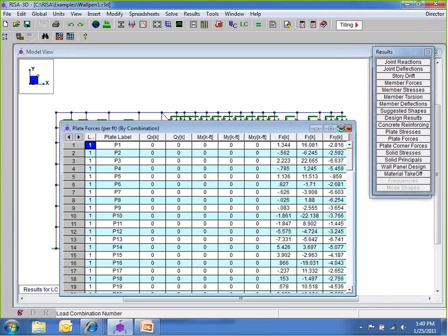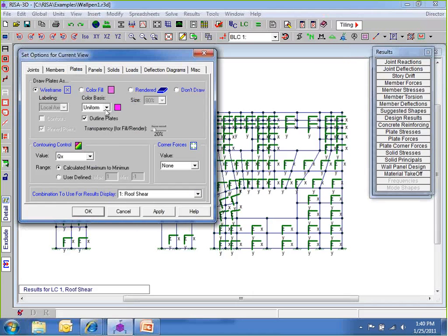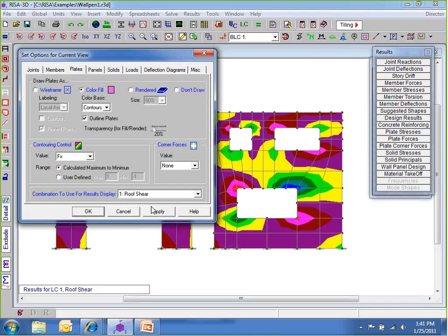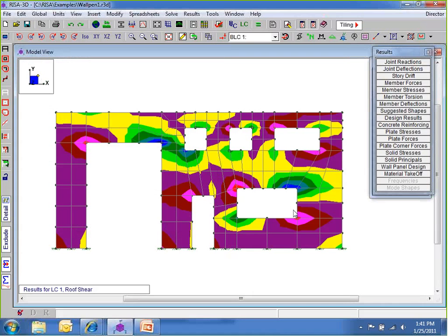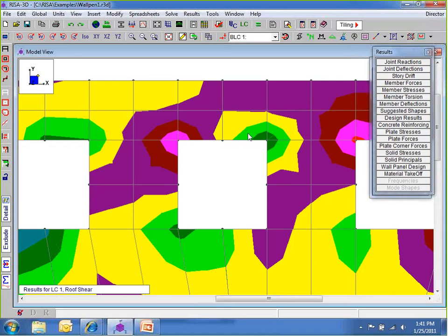But what's going to happen is when you go to display the coloring of your plates and we look at the contours, for example FX, what we're doing is mapping this. We use 4 Gaussian points inside of that plate, and then we map those just like an orthogonal map. If things are flip-flopped, we won't be able to do that properly.